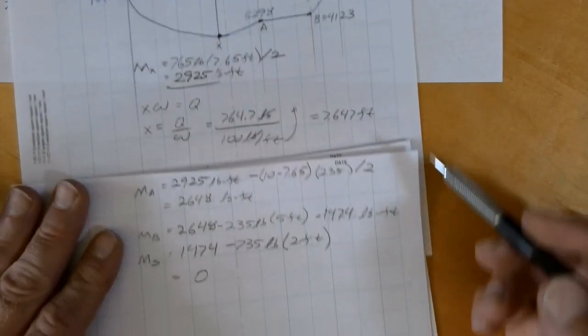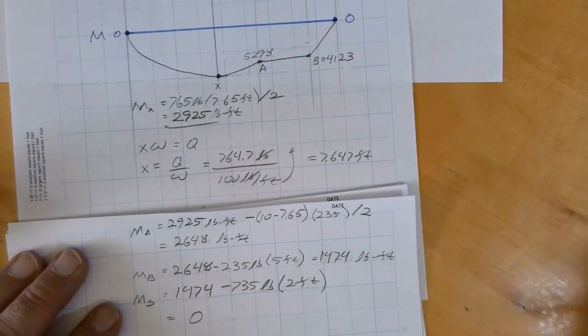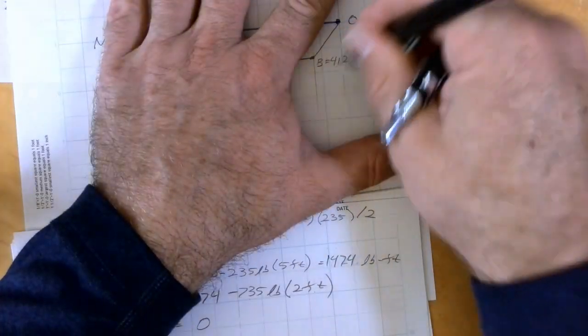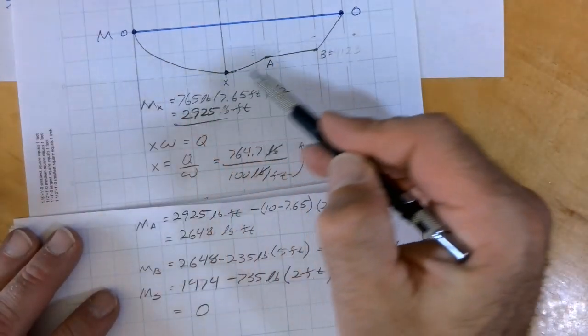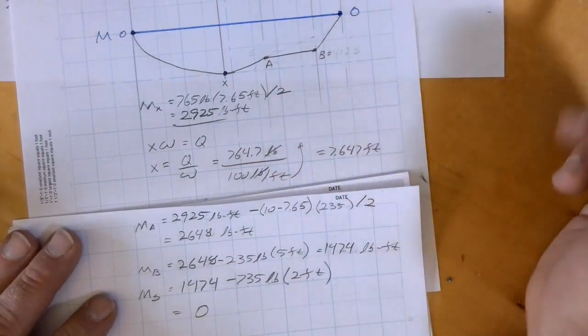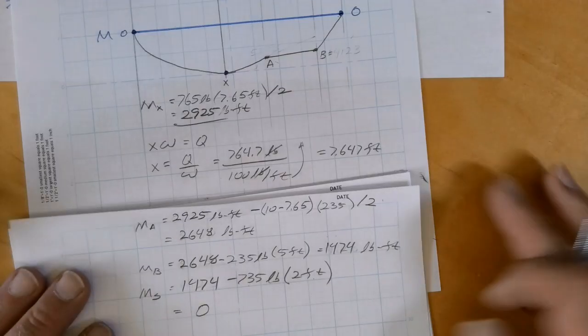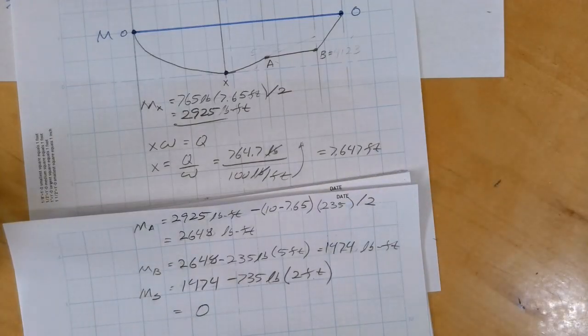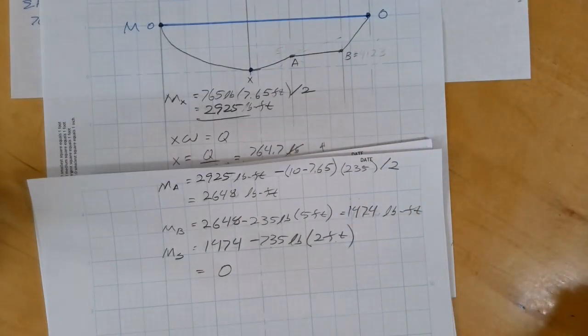Okay, bottom line is, in the end, when I do this first moment correctly, my magnitudes are correct. They're not written correctly here. I'm just going to erase them. And at the end of the day, my moment closes, which again is a check that I did it right. And so there's two ways to know if you do it right. One is to do your calcs right and check them and make sure you're correct. And a lot of times in our calcs we don't have a check, so we have to do that. Another way is just to close. If I can close my moment diagram or close my shear diagram, I know I'm correct because there's no other option but to be correct when they close.